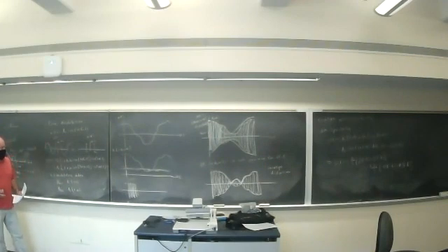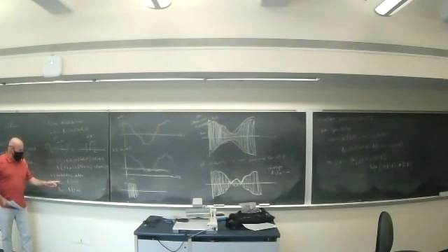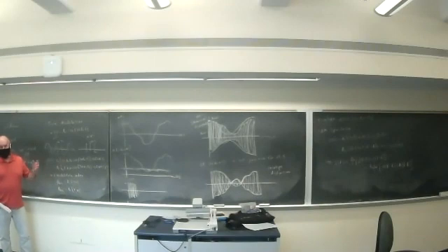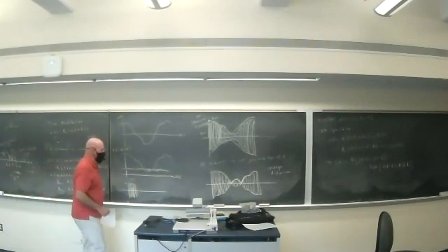Okay. Now, why are we doing this? Well, it's easy to look on an oscilloscope and figure out what A max and A min are. You'll do this on one of your labs, actually. You'll have to look at the modulated waveform and figure out what the max and min are, and then calculate the modulation index.